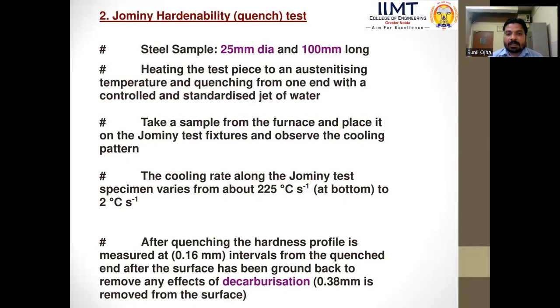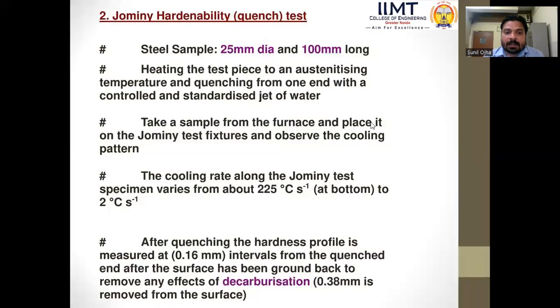After quenching, the hardness profile is measured. The hardness profile is measured at 0.1 mm intervals from the quenched end after the surface has been ground back to remove any effect of decarburization, which means 0.3 mm is removed from the surface.